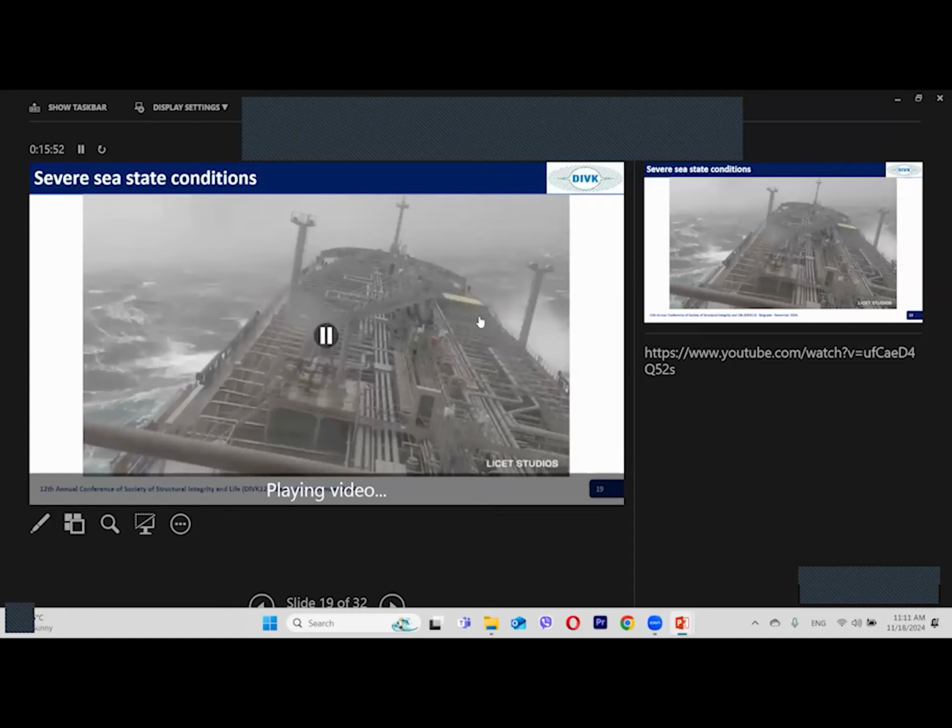You can see on this slide the ship on the sea. Regulatory bodies require us to apply sea water pressure and wind velocity. Also, you can see that there are big accelerations due to ship motions. The biggest acceleration here is going in line with the z-axis.